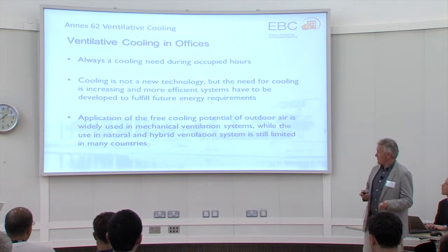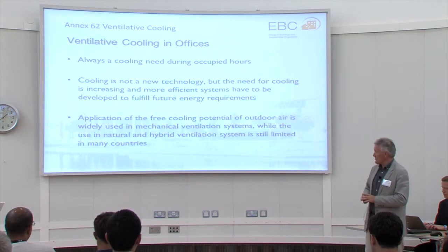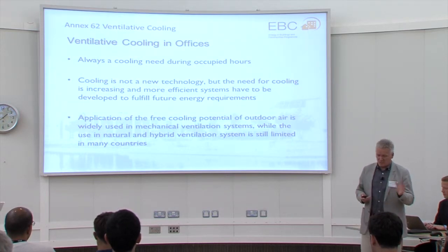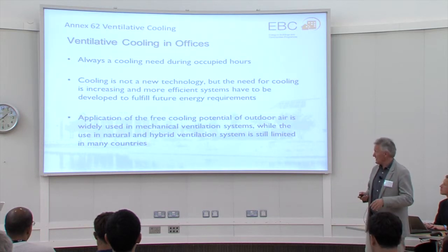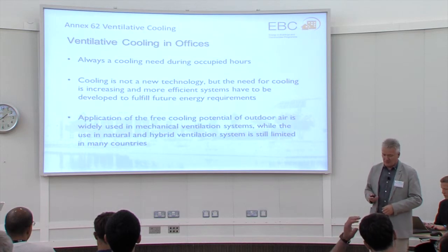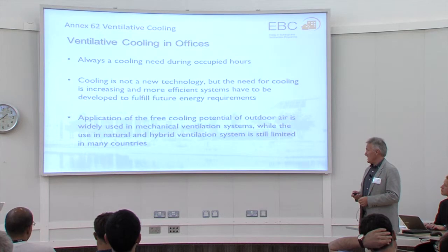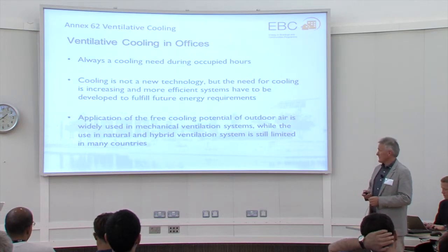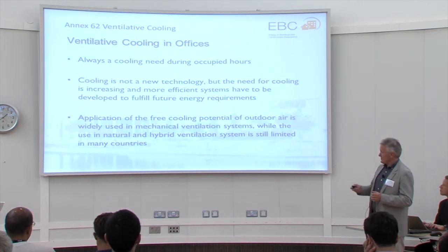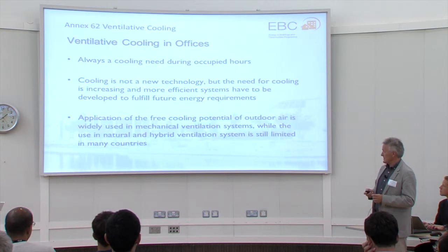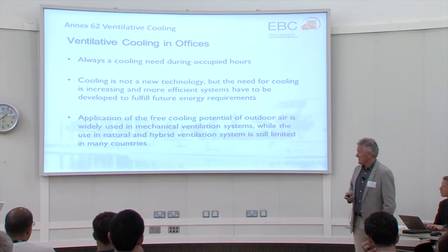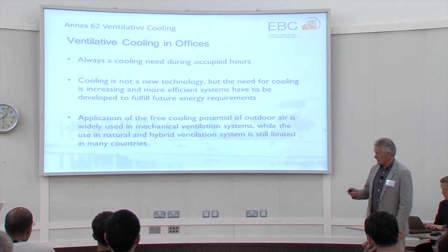If you look at the free cooling potential, this has been widely used in mechanical ventilation systems. I'll come a little back to how we can improve this, because still if we use the free cooling potential, we might still have a large energy use for transportation of air in the building. But if you look in offices, then you could say natural and hybrid ventilation systems are still limited in many countries for ventilative cooling purposes.